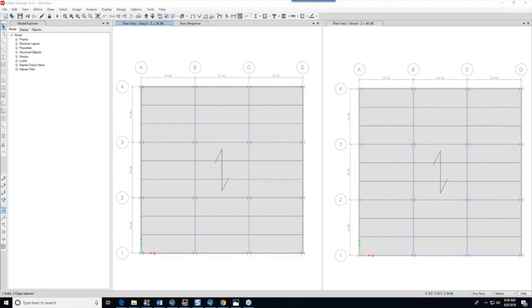The disadvantage of that, though, is that you have to manually assign the gravity loads as part of your column. And if you're conducting a P delta analysis, you really need the entire mass and weight of the structure. So in order to account for that, you would have to model a leaning column, let's say, and it's just more burdensome for you to do that. So oftentimes it is just simpler to model the whole building. But that being said, engineers, I think, need to use some judgment.